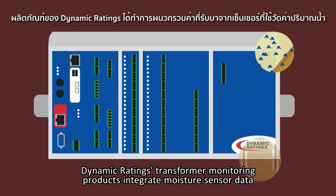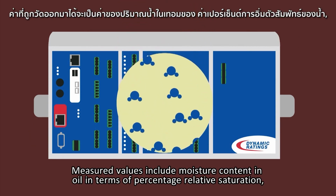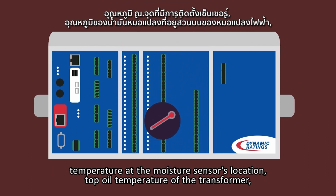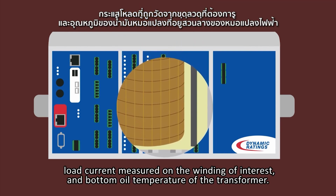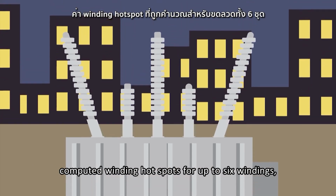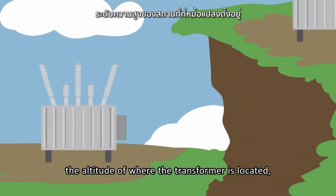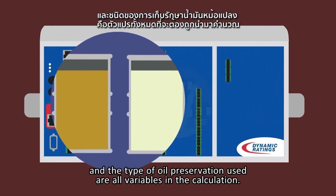Dynamic Ratings transformer monitoring products integrate moisture sensor data and other parameters as part of the moisture management model. Measured values include moisture content in oil in terms of percentage relative saturation, temperature at the moisture sensor's location, top oil temperature of the transformer, load current measured on the winding of interest, and bottom oil temperature of the transformer. In addition to moisture data, transformer characteristics such as computed winding hotspots for up to 6 windings, type of insulating fluid, the height of the oil above the hotspot, the altitude of where the transformer is located, and the type of oil preservation used are all variables in the calculation.